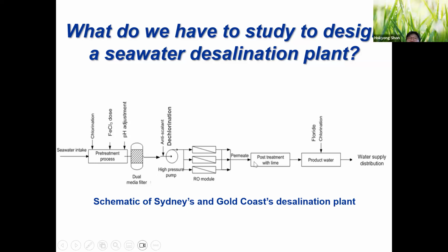So high pH 8 is not really suitable, as you get a lot of inorganic scaling, like a stone in your pipeline and reverse osmosis. So we reduce the pH from 8 to 6. So you can put H2SO4 or HCl to adjust your pH to avoid the inorganic scaling.